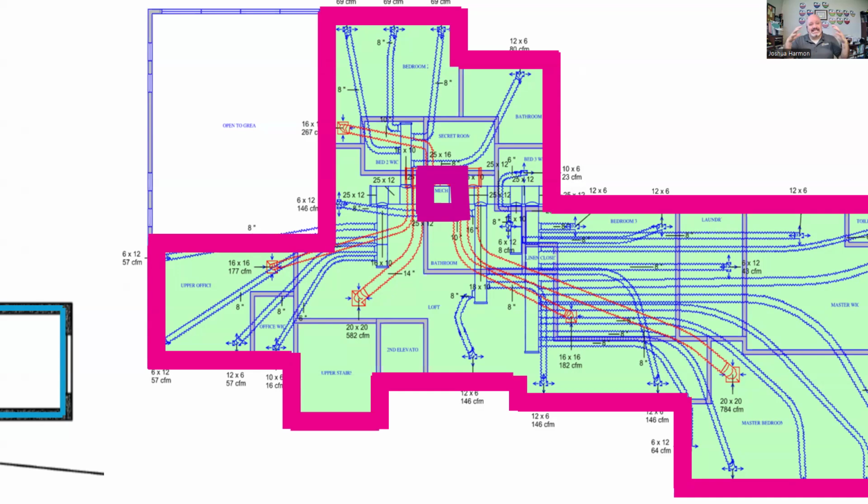As long as it's inside that conditioned space, that leak will actually still be within the control of the building. If it's outside, then we're just losing conditioned air into a space that, again, wasn't intended to operate, which can, again, affect how the mechanical systems operate.